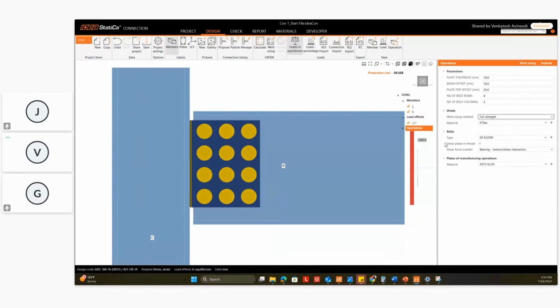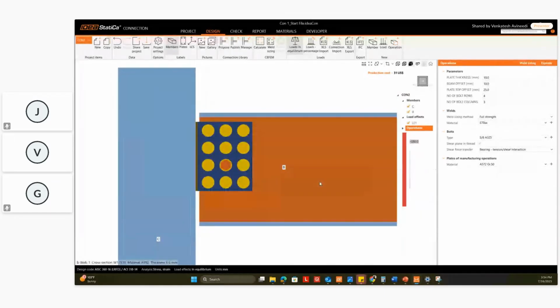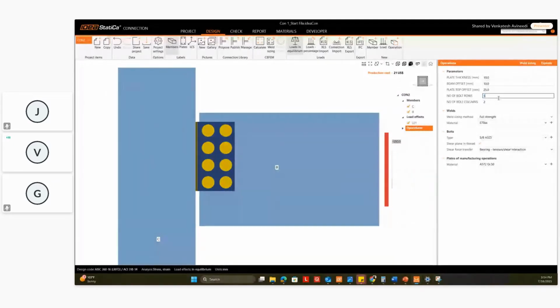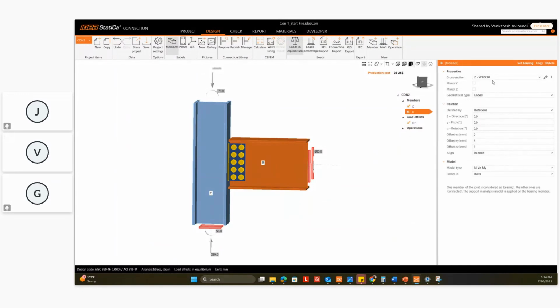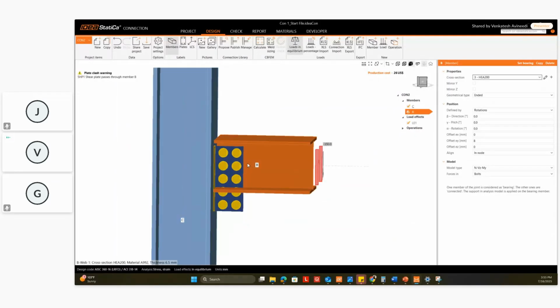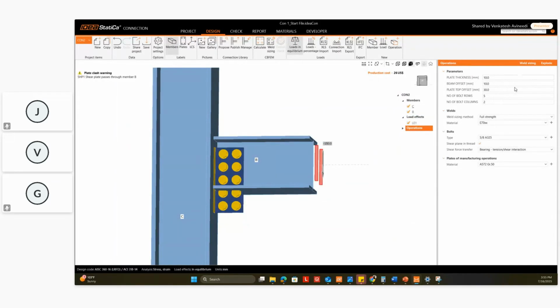And hence if I change the bolt diameter to something else, then the plate dimensions will be automatically adjusted, and I can increase the number of bolts and even offset the plate. So if I have a new connection, like maybe instead of this I have an HEA200 beam, then if I apply this template, then in a few clicks it's edited.